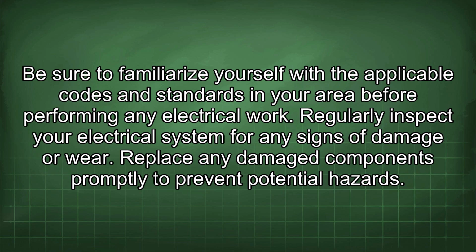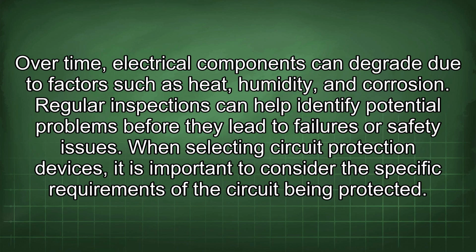Regularly inspect your electrical system for any signs of damage or wear. Replace any damaged components promptly to prevent potential hazards. Over time, electrical components can degrade due to factors such as heat, humidity, and corrosion. Regular inspections can help identify potential problems before they lead to failures or safety issues.